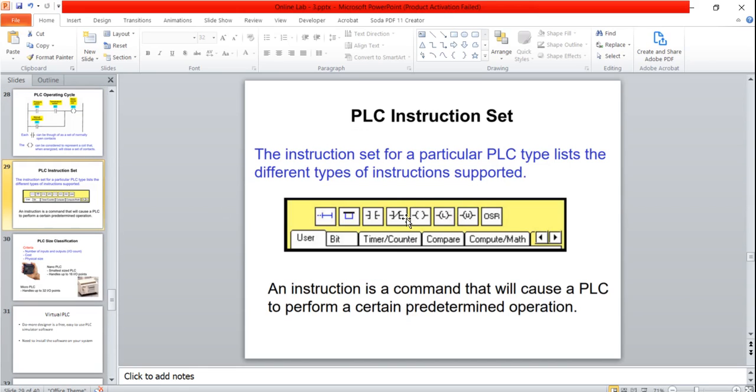But the PLC is a very powerful tool. You can use different things. For example, you can use a timer. So let's say after I press a button, the motor should run after 5 seconds. Or let's say in the case of a counter, once I have processed putting a cap on 50 bottles, my PLC should close. So in order to keep track of that number, I can use a counter. I can also do different things such as mathematical expressions or comparison operators. Again, there are so many different options, and we will look into this in the coming labs.